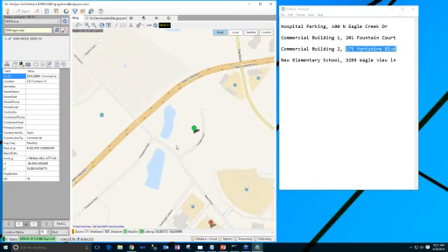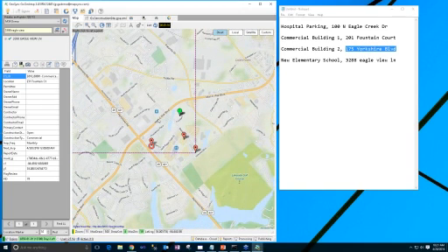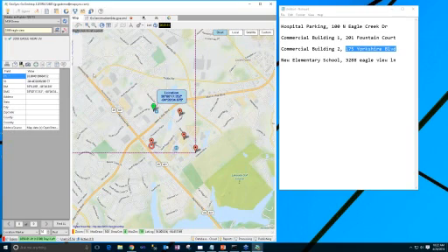So let's go back and revisit. We can set points. Points are set workflow specific, so you have to use a workflow layer, so you have to have a specific purpose for that. In order to set points, you need to make sure your desktop software is configured properly, the layer is set, and then to set a point, you can right-click and set a user marker on the screen.